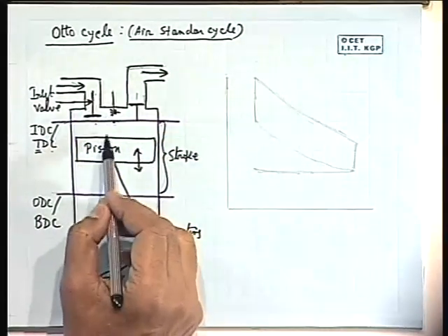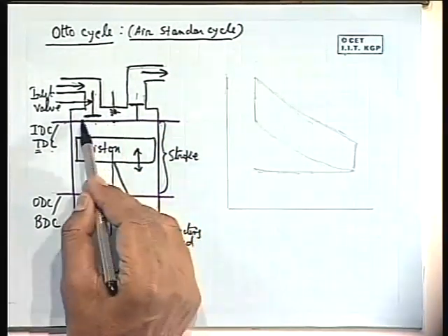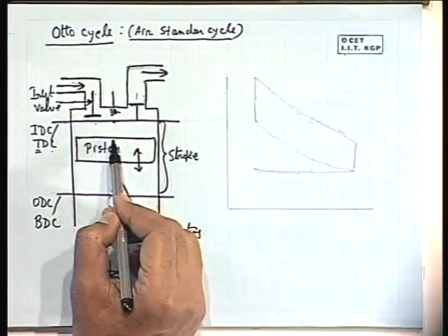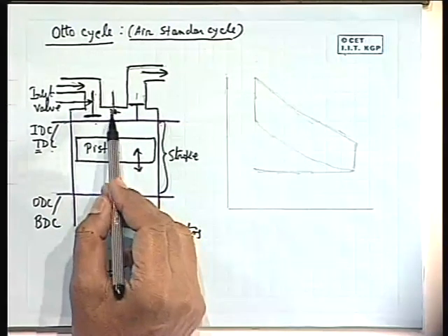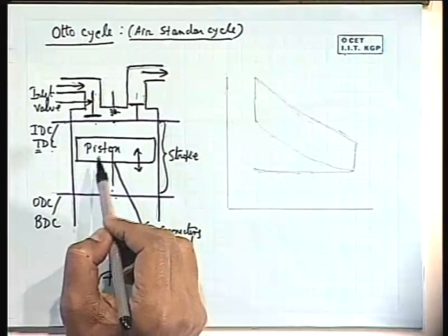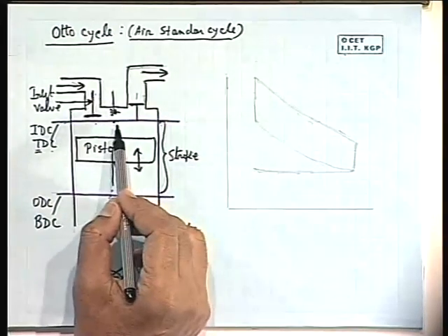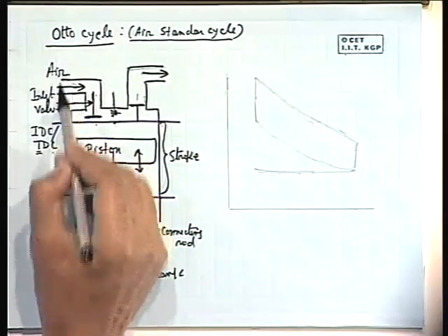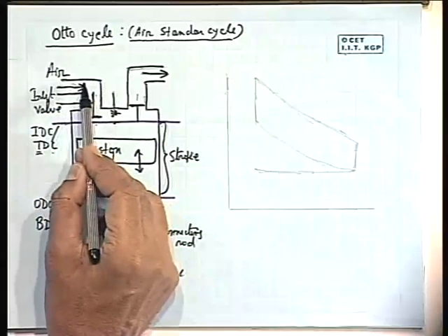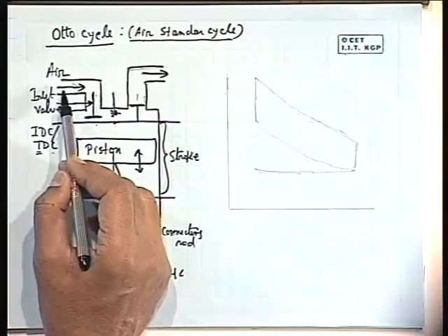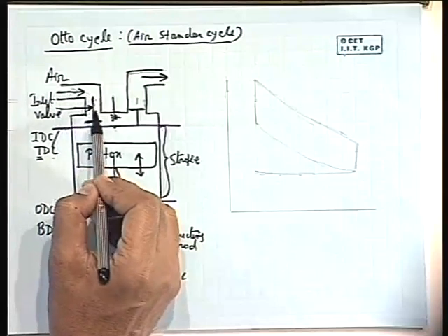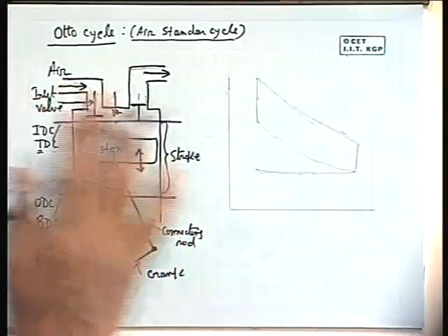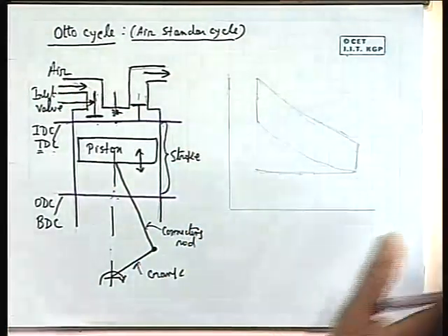What happens is that when the piston is descending, the pressure inside will be less than the atmospheric pressure, because the gas at atmospheric pressure has expanded, so its volume is increased and pressure is decreased to less than the atmosphere. So there is a suction pressure inside the cylinder. Then fresh air from outside, connected by a pipeline known as the intake manifold, comes through this intake manifold into the cylinder. These are the usual terminologies. This is the most idealized case I am describing; there are many things, air filter and others, which you will be reading in the IC engine class.